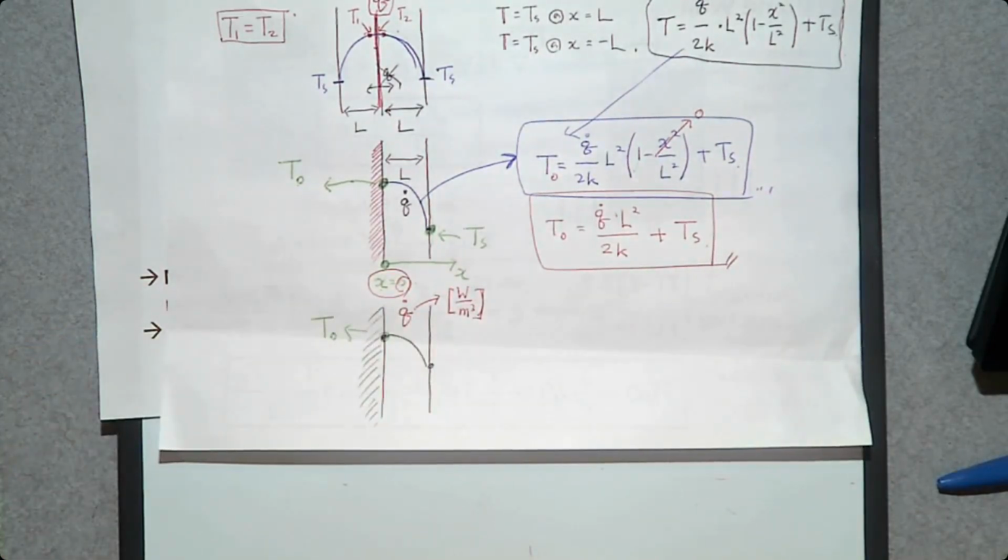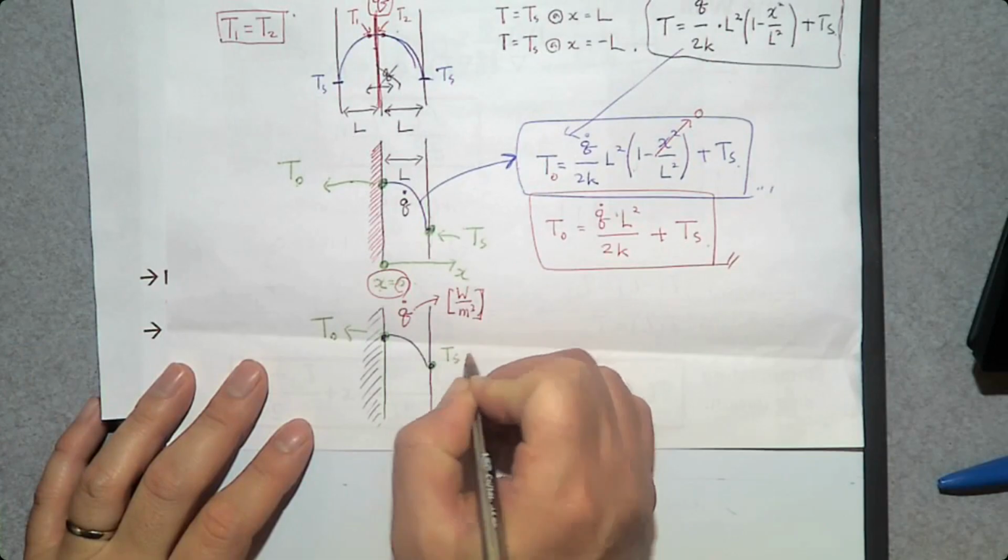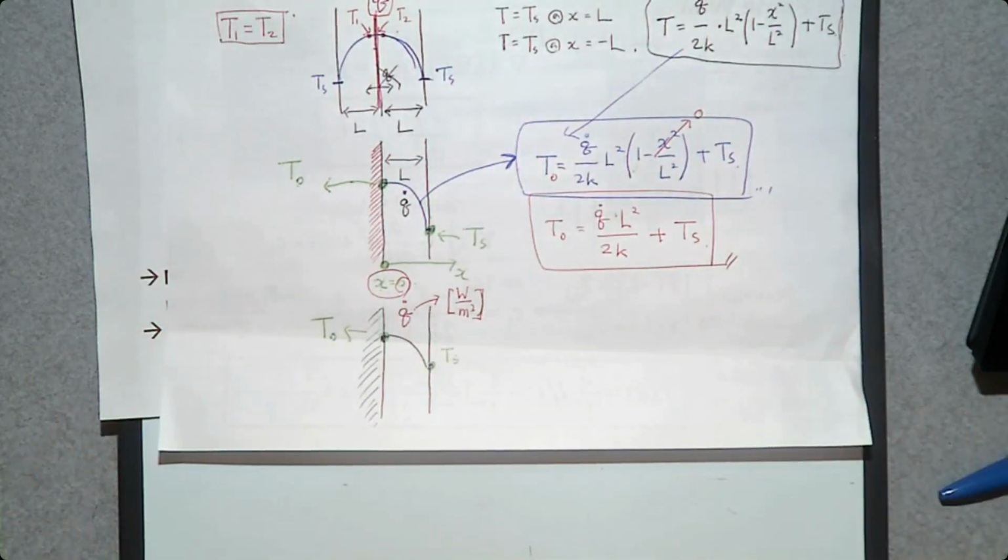What about if the temperature goes up or down? Then that's a transient heat conduction problem that we can study in chapter 5. So let's assume that we have a steady state heat transfer problem. Since there's a heat generation, we need to get rid of this heat. Otherwise, the temperatures of this plane wall are going to increase.